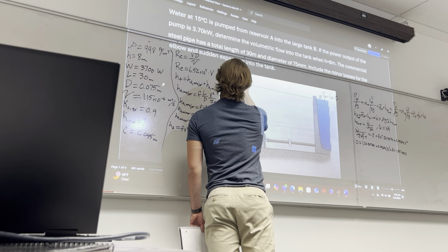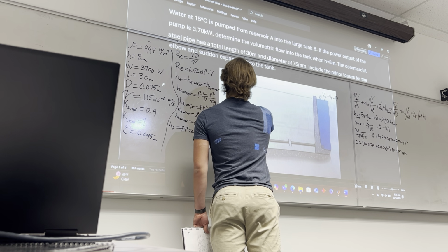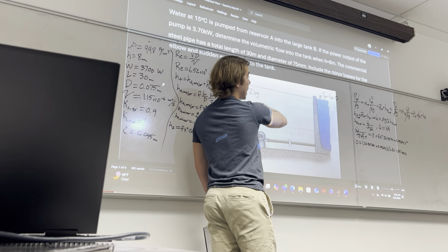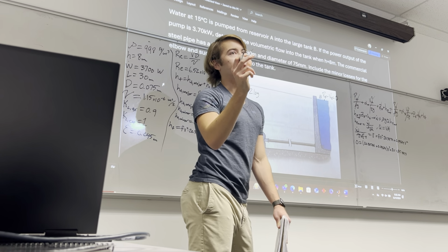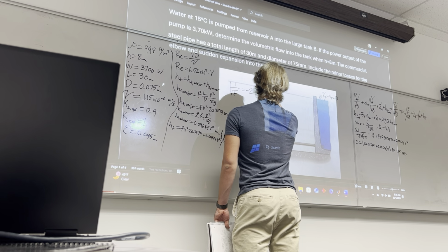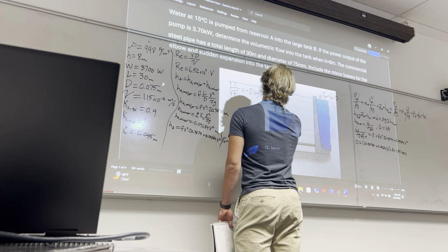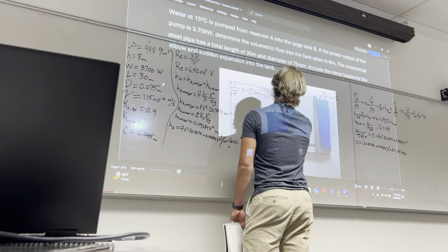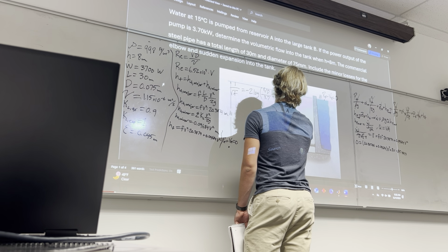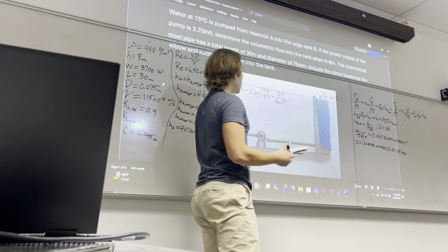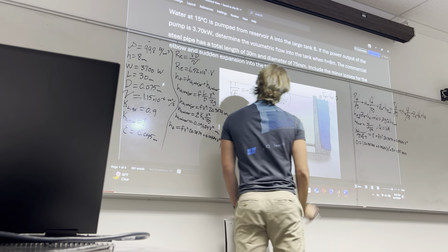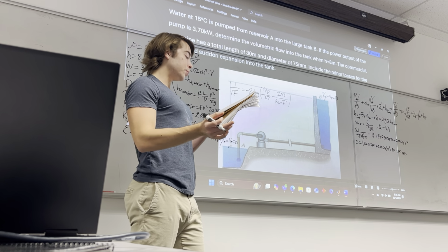So we got Colebrook. It's 1 over root F equals -2 log. And this is log base 10, not like natural log. On your calculator, use the LOG button, not LN. Then epsilon over D over 3.7 plus 2.51 over Re times root F, all right? And it's kind of an equation soup looking thing, but it's really not bad. So how you go about solving this, right?